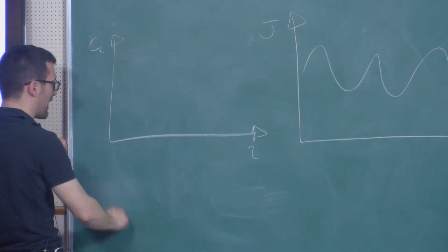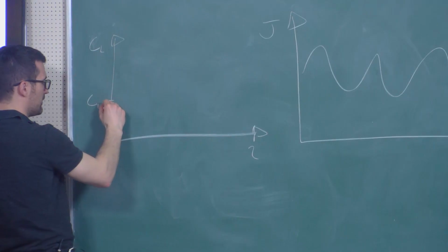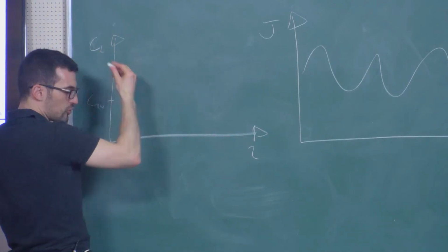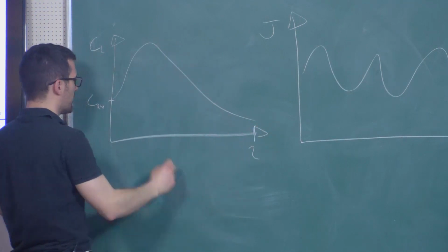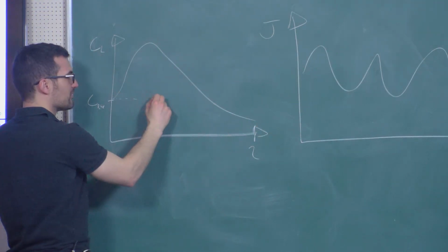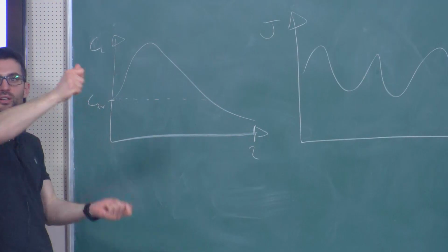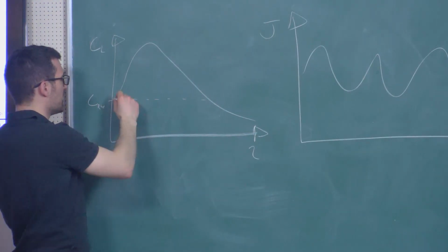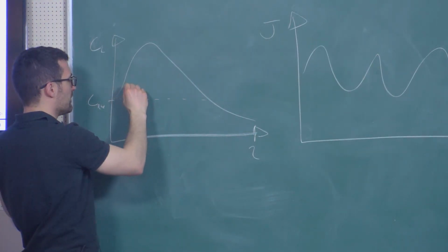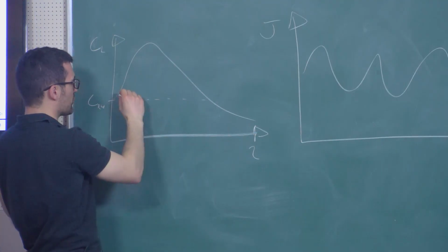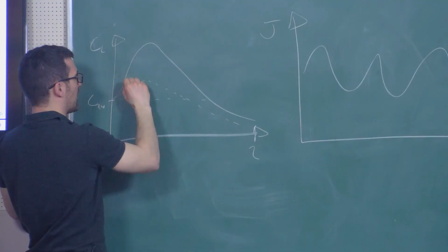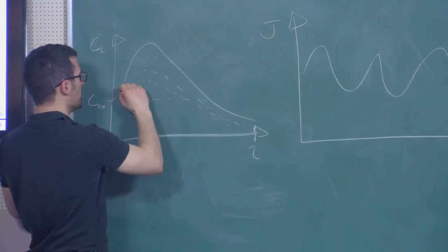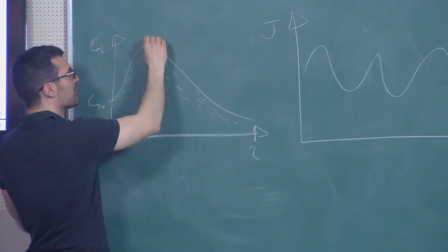So assume that you have a hydrogen concentration from the environment, that is Cm, and assuming conventional plasticity, at the steady state it is going to be something like this. Initially, at t equals 0, there's not enough time for the hydrogen to follow the hydrostatic stress. Eventually it starts following the hydrostatic stress. So this is at the beginning, a bit later on, and then eventually you get there.